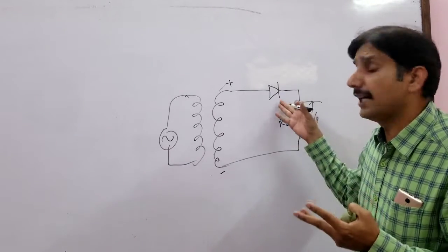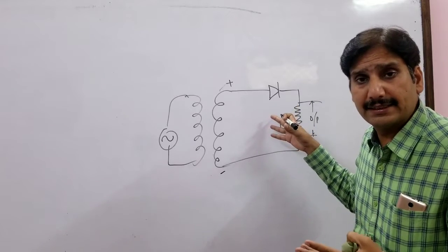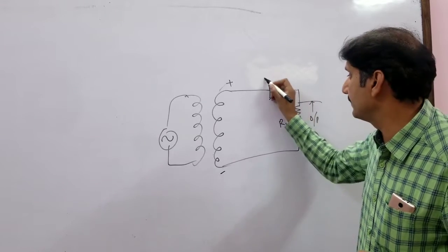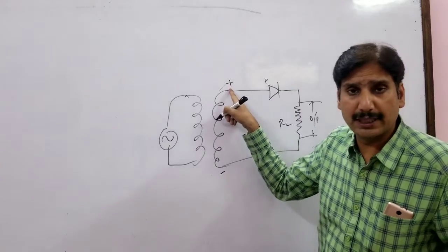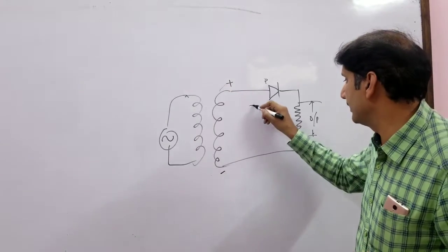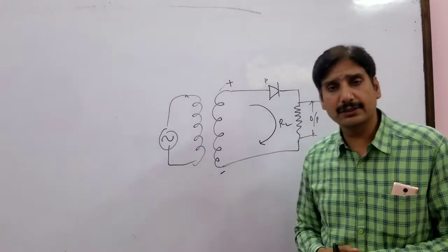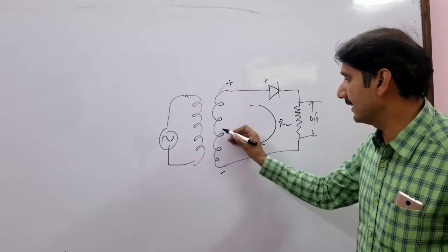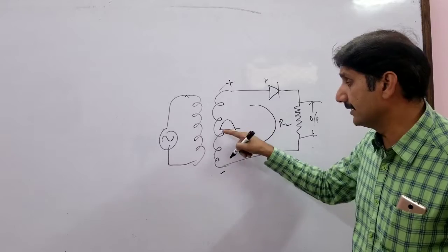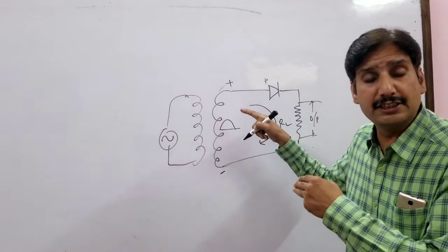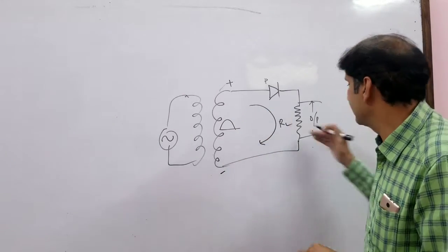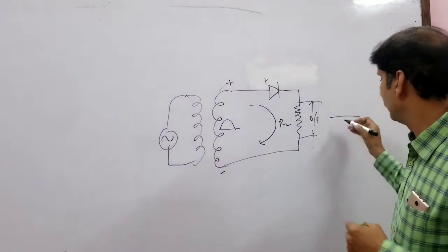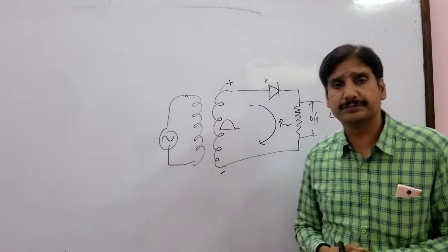The diode in this case is forward biased at this instant, because the p side is getting the positive polarity. Therefore, the p-n junction is forward biased and it will allow the current to flow. That means as the current in the input increases, achieves its maximum and goes down, the same thing will happen at the output.